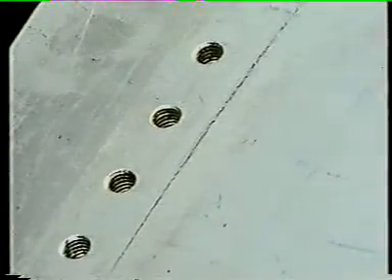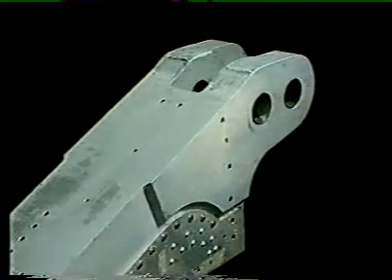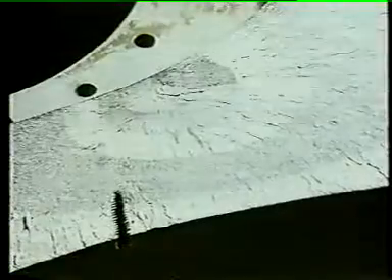Some alloys prone to exfoliation corrosion, when used in certain components, such as this section of Canberra, will also be liable to stress corrosion cracking. It occurs particularly when the metal is subject to periods of tensile stress. Even minor damage to the surface protection may lead to cracking, despite little corrosion being evident.